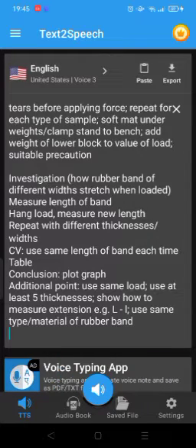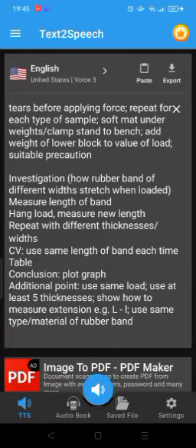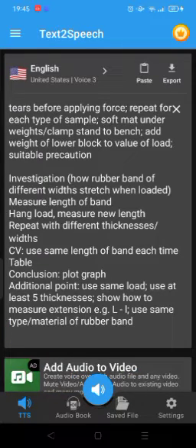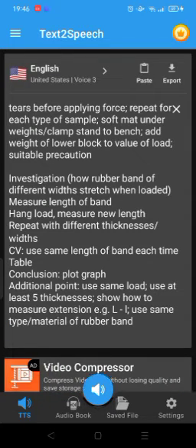Take readings from 50.2 centimeters, or place the pivot at the 50.2 centimeters mark. How to make sure the center of the block is at the 40.0 centimeters mark on the rule: measure half the width of the mass either side of 40 centimeters. Mark the center line of the mass and align it with the rule.